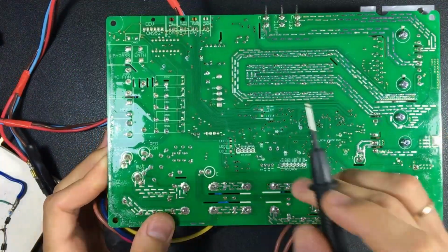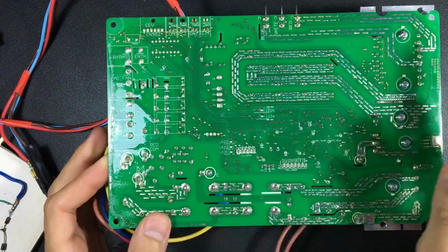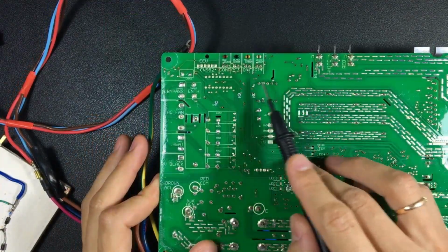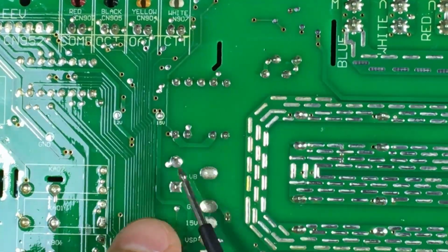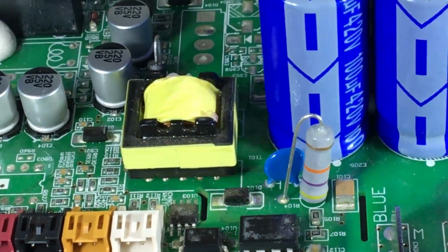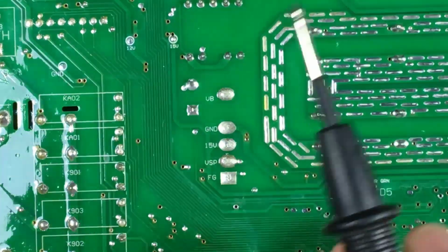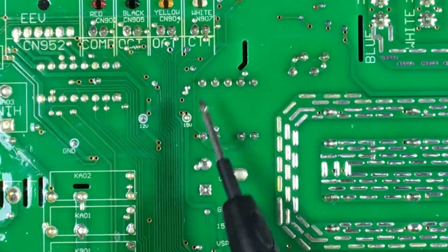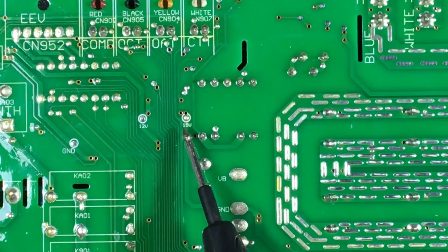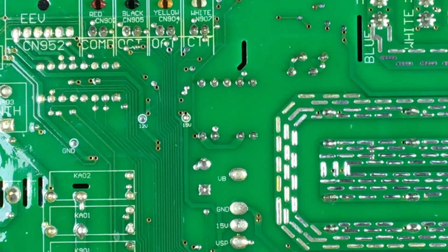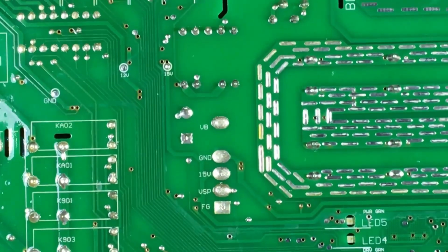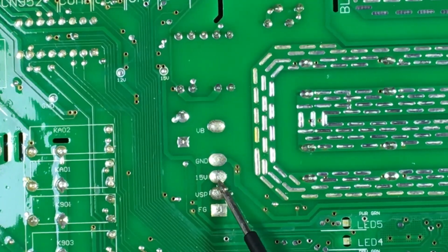Let's go this way, leaving the switch mode power supply. Let's zoom in on this area. There it is, here where we have the transformer and the other side of the switch. Starting from here is where we generate the 15 volts. These 15 volts, notice that we even have a checkpoint here. Here we have the 15 volts. They are derived on one side to this point.